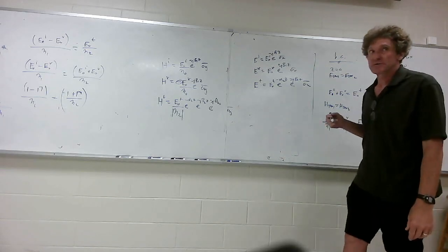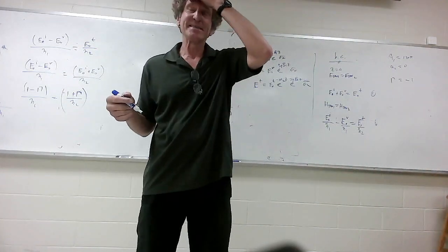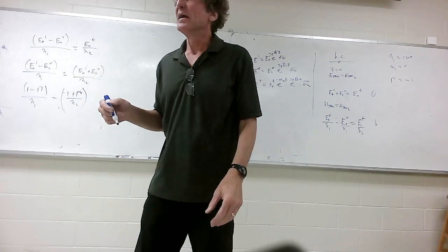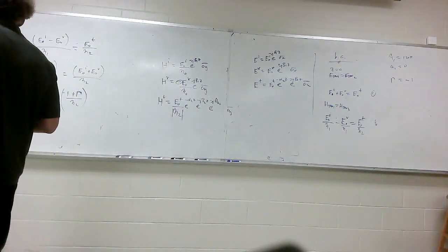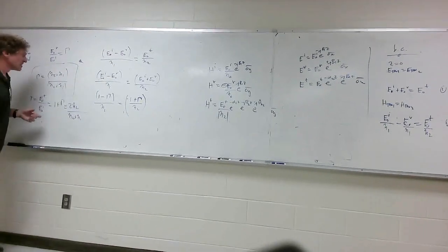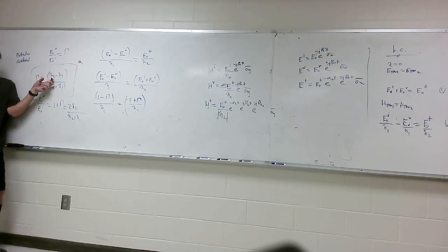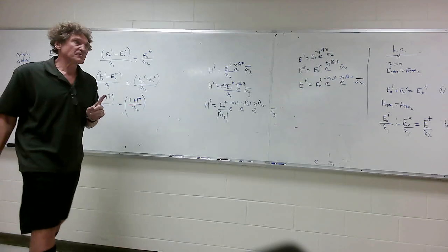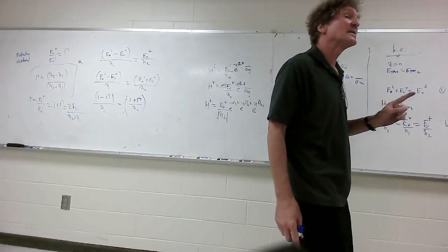Now suppose the opposite, well, you can't actually do the opposite, but the other extreme possibility, and it will never get to this value. What if eta 2 gets very large? Just listen to me. Instead of 120 pi, say it's 120,000 pi. Well, then it's really eta 2 minus 0 over eta 2 plus 0, or it's 1. With me? So the extremes for reflection coefficient are from 1 to minus 1.